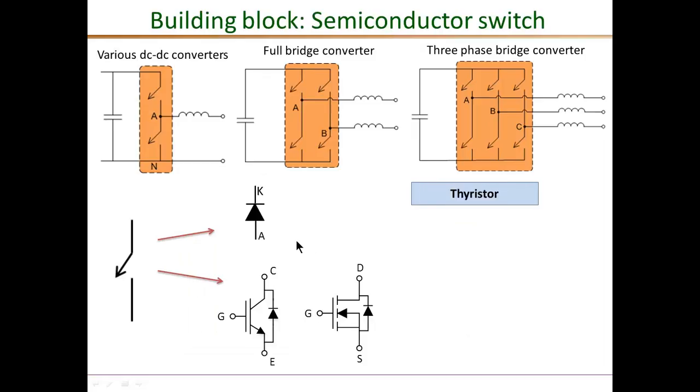In fact, the switch has been the main driver of the evolution of power electronics. Power electronics started with thyristors and with line frequency switching or force commutated switching at a few hundreds of hertz. Then came the bipolar junction transistor, which really started the era of switch mode power electronics and achieved switching frequencies in the several tens of kilohertz. Then the MOSFET completely revolutionized high frequency switching, pushing the frequencies into several hundreds of kilohertz and with excellent efficiencies.